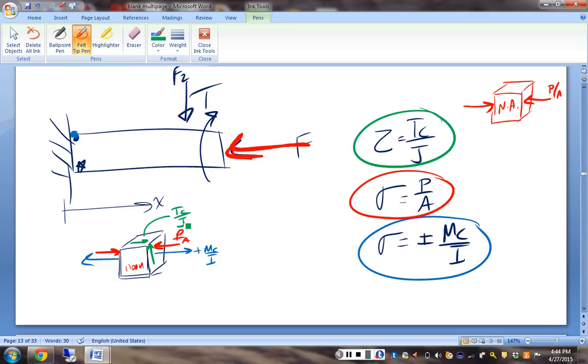Okay, push down on this. What are the forces of the magnets? Which direction are the magnet forces holding the pieces together? The magnets are in the X direction. Okay. So you can think about it like these little molecular magnets are trying to hold the stuff together. And in which direction is that making tension on the top? In the X direction. In which direction is that squooshing them together on the bottom? Like compression? Does that help?